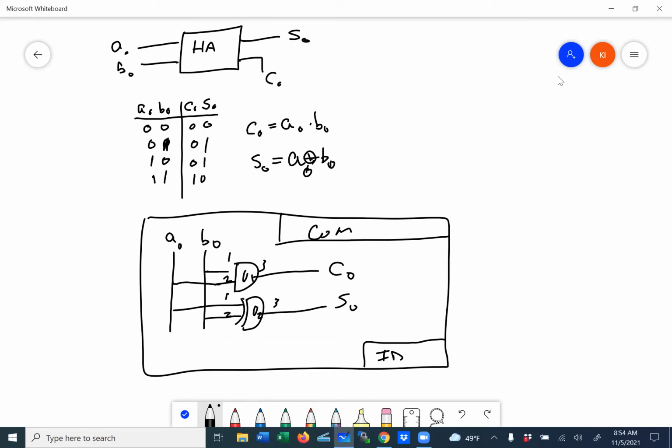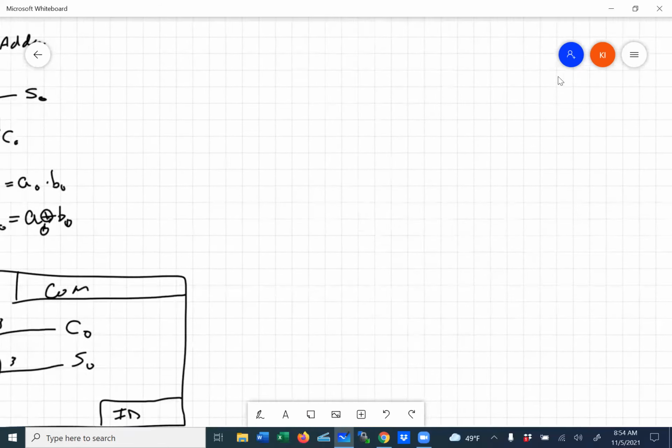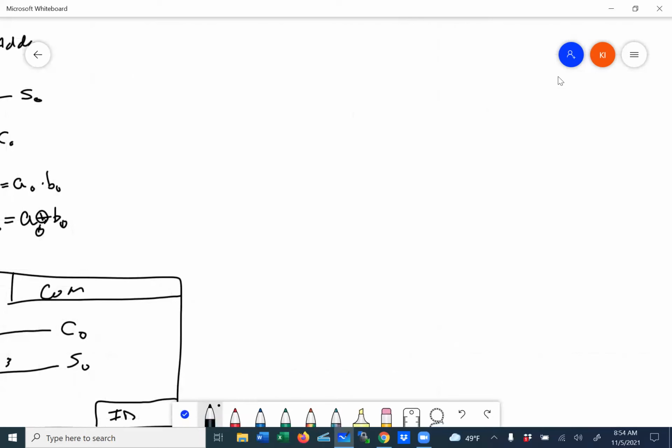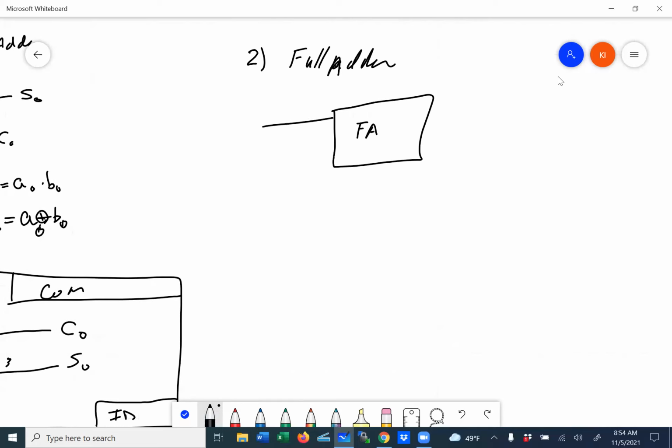and you say, go back and look at the reference that I just gave you earlier. So the next thing you need to do, which is a little bit more complicated, is you need to do the full adder. So the second step in the process is to design the full adder. And the only difference the full adder has with the half adder is because when you have your full adder sitting here, not only do you have the two bits coming in, A1 and B1, you also have another carry from the previous bit that comes in.